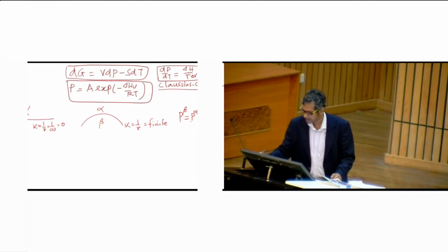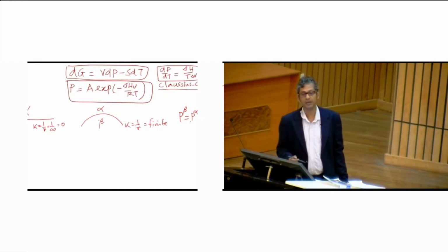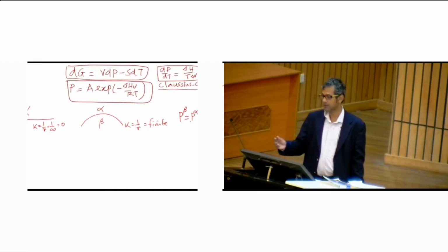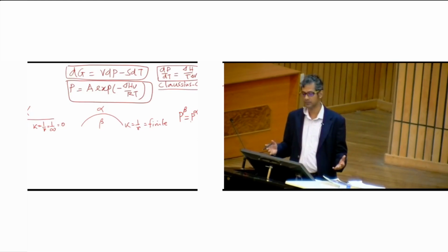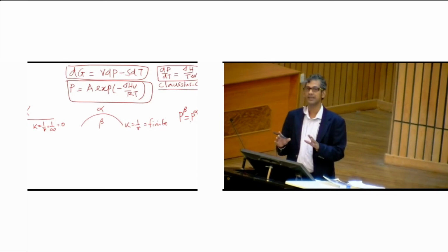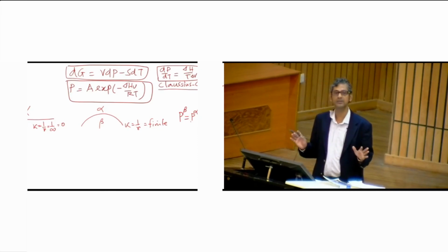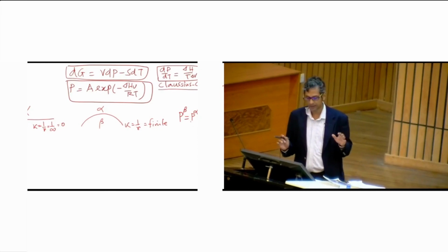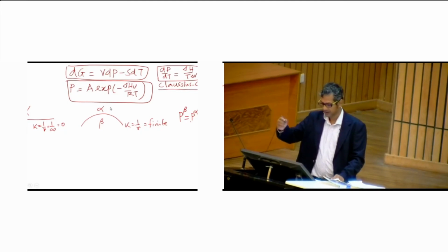That is nothing but surface energy multiplied by kappa, the surface energy between beta and alpha, and kappa is the curvature, that is gamma by r. Obviously there will be some constant, sometimes 2 gamma by r, sometimes 4 gamma by r, depending on different geometries. Let us forget about it. For simplicity, this is related to gamma into kappa, and kappa is related to r. This is understandable, right?